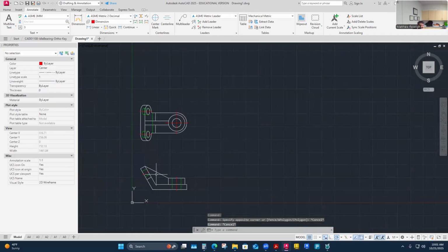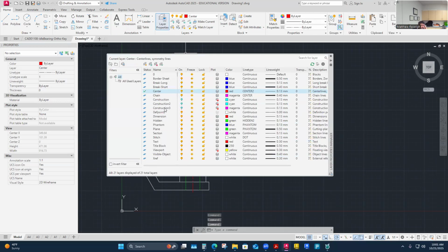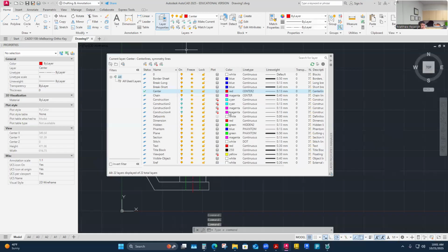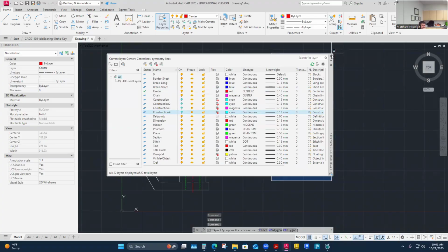And then it's time to work on the auxiliary view here. Once I finish the auxiliary view, I'm ready to dimension for the most part. I can't see that I'm missing anything necessarily. Auxiliary view, let's do it. I'll probably build it on an additional construction layer to start it on its own, with some unique name. I'll copy my last one, and it doesn't matter what color, but I'm going back to the original construction color.